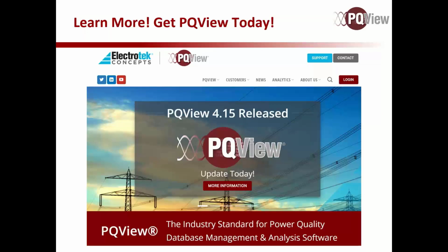We have a question about analyzing the data about the incipient failure slide. That was provided by a customer. I'm not sure if I can actually speak to it. For fault location, we're analyzing the waveform and we're calculating the fault reactance. So we're calculating a reactance value using positive, I want to say it's positive sequence reactance, not traveling wave, no. We're using positive sequence reactance to fault.